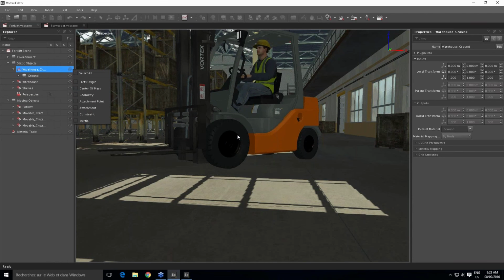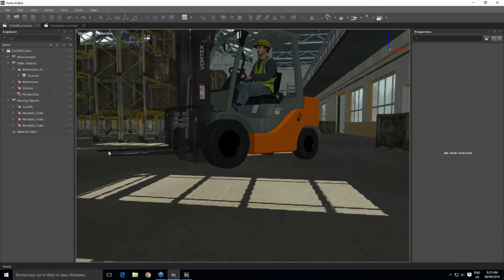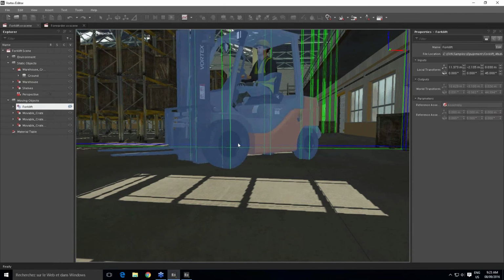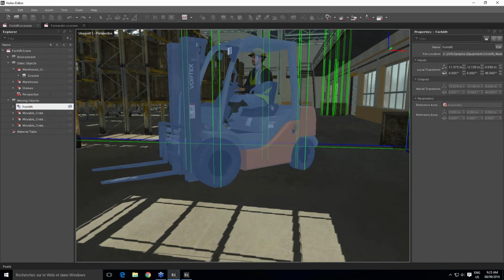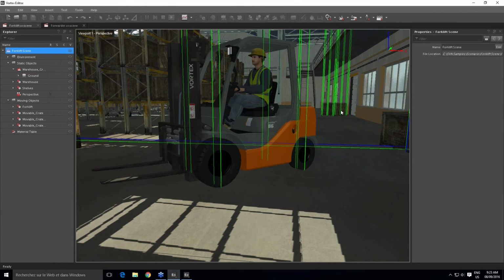And this time I'm going to use Shift-C. Sorry about that. Click in the viewport. There we go. Shift-C to display our contacts in the scene. So you can see that the box has integral slip displacement enabled because we don't want the box sliding around if we have a slope. Right now the warehouse doesn't have one, but eventually we're going to want to add a concrete ramp, and it wouldn't be good if the boxes were sliding down the ramp as we deposit them at this location.